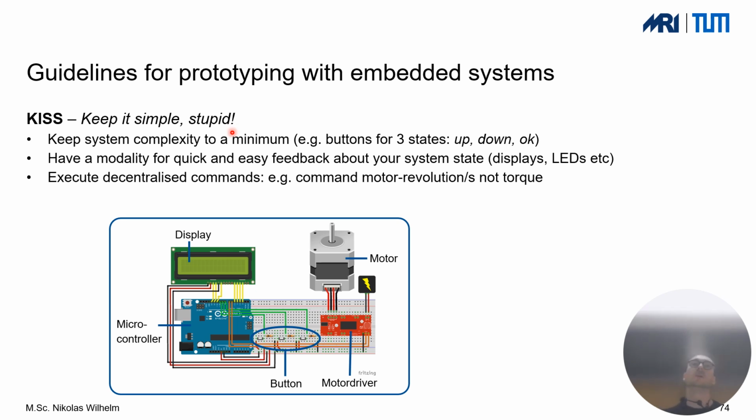Because if you overcomplicate things, if you add too many sensors that you actually have no real use for, your system gets more bulky. Also, the requirements increase because all these different new sensors might require you to use extra pins or extra voltage supplies, and your system just blows up. So try to keep the complexity to a minimum.